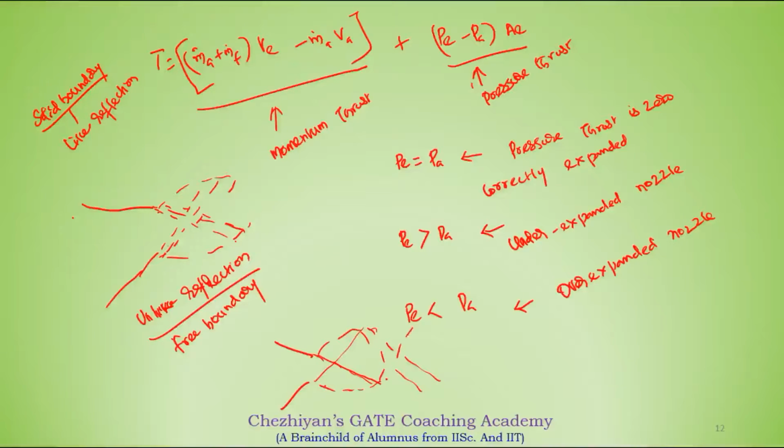Normally in the exhaust coming out of an aircraft engine or a rocket engine, you can see very clearly a diamond-like pattern. That's because of this unlike reflection. For balancing P equal to PA, the energy coming out has to be converted at the end, so you have successive reflections. We will be discussing that in detail in the propelling nozzle section.